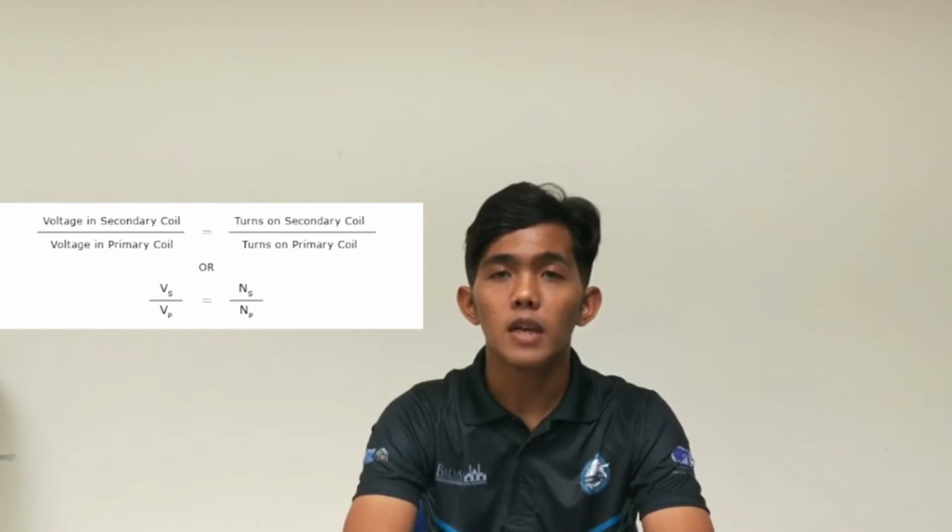The transformer is also used to split voltage equally to half wave in full wave rectifier. The basic equation of transformer is Vs over Vp equal to Ns over Np.